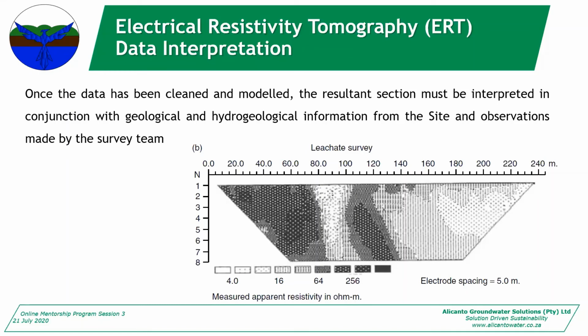The other ones give you a single line with one sort of depth range. Like you think about your EM, if you run a 40-meter EM survey, it's going to be penetrating between 15 and 30 meters at best, average 20 meters. Whereas your resistivity is going to go from 5-meter penetration all the way down to 100, 150, 200 meters even. So you can get a bit more variation, and it'll show you stuff. It'll show you the weathered zone. It'll show you your fault zones. So that's why I say it's a bit easier.